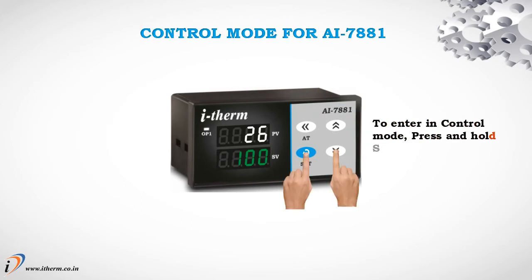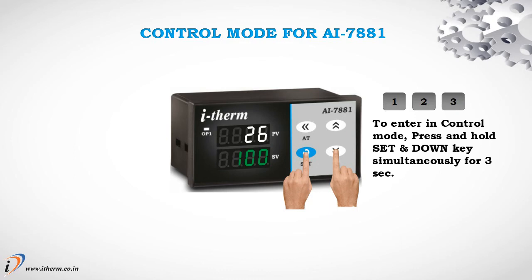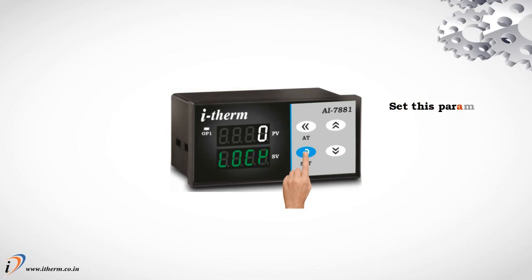Control mode for AI7881. To enter control mode, press and hold the Set and Down keys simultaneously for 3 seconds. Set this parameter to 15 to access the control list.